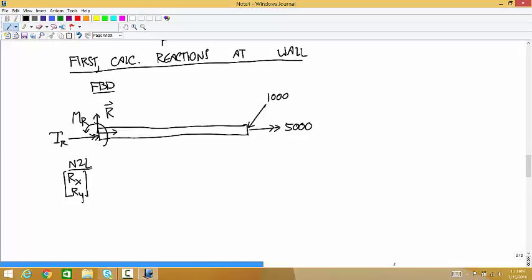So there are two kinds of moments going on. This force is applying a moment that's trying to bend, to rotate it this way. And then this torque is trying to make it spin about its axis. We need components of couples at the wall to prevent both of those types of motion. Any other questions about that? So the new thing that we didn't do in statics is this axial torque. That's a new one.